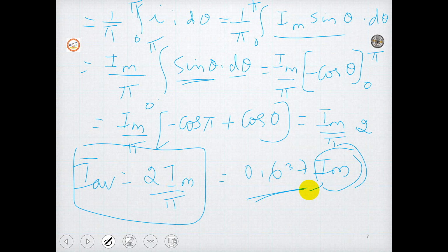So average value is used for many applications. Why we need average value basically, because many applications like battery charging take up the average values. So the charge transferred in a capacitor circuit is measured using average values, and the average value is indicated by DC ammeters and voltmeters easily. The average value of a purely sinusoidal waveform is always 0. So it plays an important role in analysis of the rectifier circuit. So these are the advantages of the average value. So in the next slide, we'll see what is RMS value or effective value.